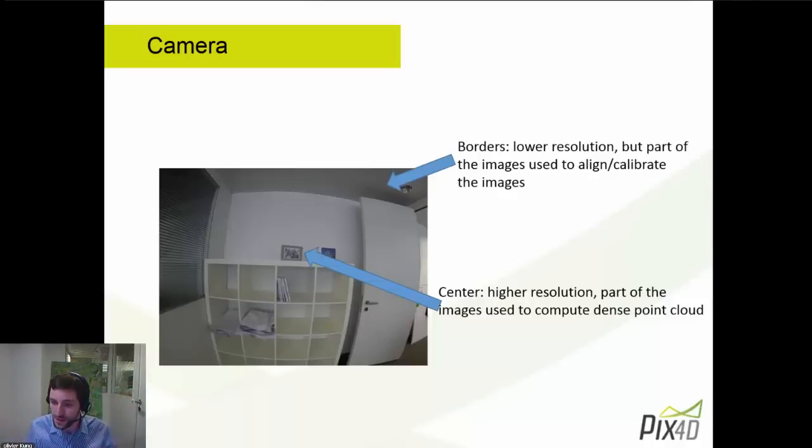And also the other good news is that Pix4D Mapper has included in it a full definition of how a fisheye lens is doing this type of distortion that makes straight lines become more curved. And thanks to that, these curves do not make the reconstruction worse. Actually, they don't have any impact on lowering the quality. Since we have the model of how these curves are formed, we are able to correct for them and to take them perfectly nicely for doing the processing.